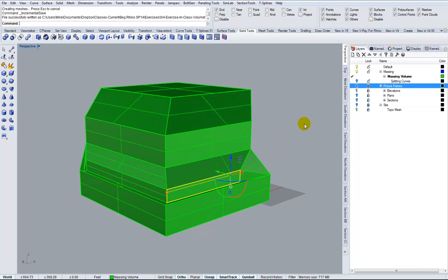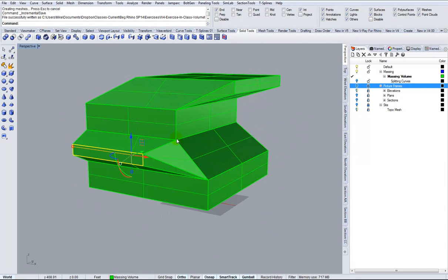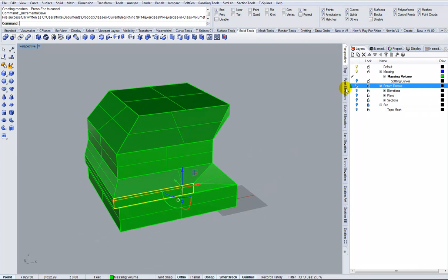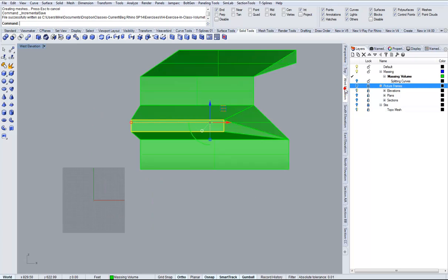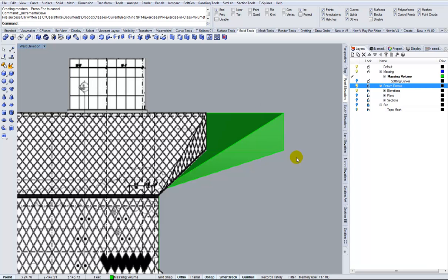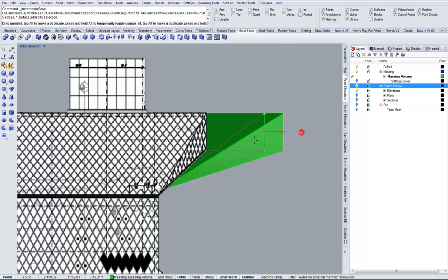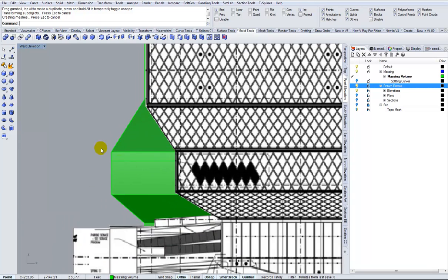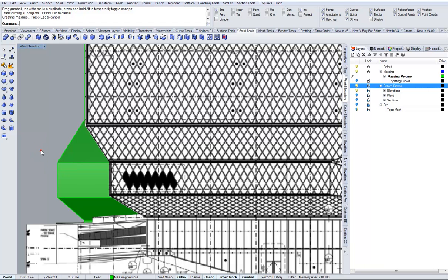But now I'm actually ready to just tighten up all the geometry. I've got all the faces I need to make the geometry of the facade, so I just have to tighten it up. And I can just go to each elevation and do that. Turn back my picture frames and just start moving things around. So I can just sub-object select my faces and start matching them up to where they're supposed to be with the snappy dragging going on there. It's not going to be a problem. If things need to start tilting for the book spiral, then now's the time we can start doing things like that.